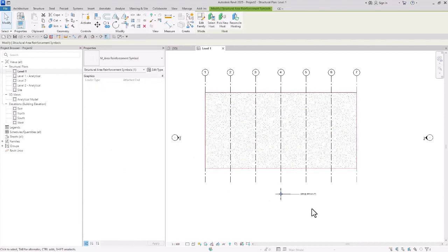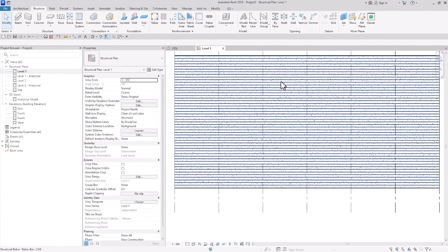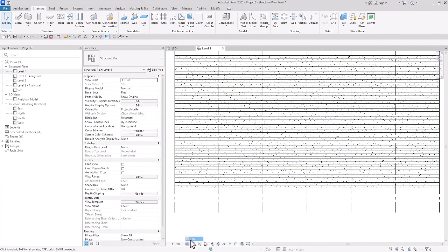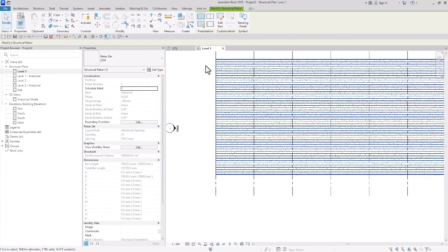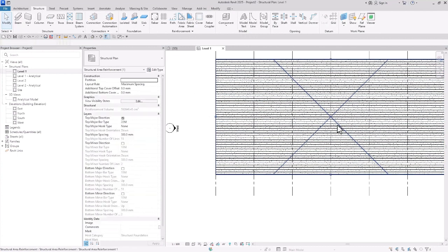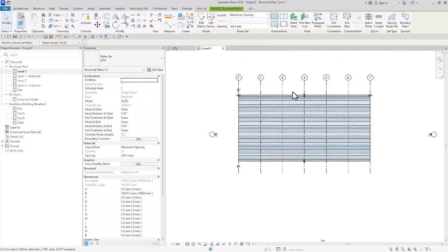And yeah, okay. Now I'm going to set this on wireframe to have a better view. Now fine. Now, as I said, if we select this, splicing won't work. So to get rid of this problem, I'm going to go to System and click on Remove. Now if you select this, a tool would appear for us in Modify Structural Rebar here called Splice. As you can see, it contains 2 items, Splice Rebar and Insert Coupler.